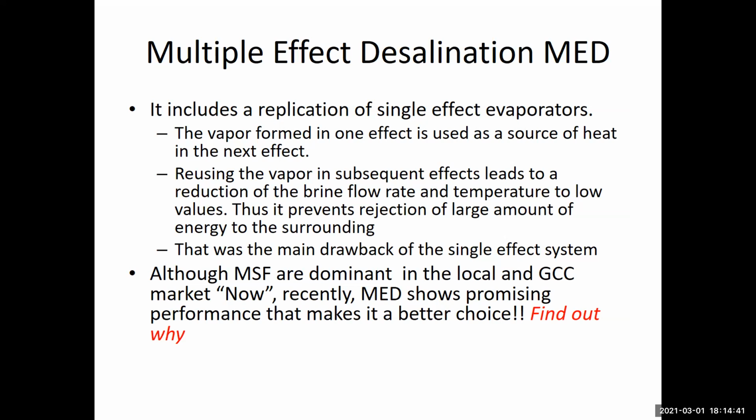Yes, we can. If you are able to do nanofiltration or reduced graphene oxide ultrafiltration to the seawater coming in, then you are able to eliminate the ions that result in scaling, and then you can increase the top brine temperature without fears. When you do that, instead of having 8 effects, you can make them 10 or 12. So instead of having a PR equal to 8, the PR can equal 12, can equal 16, depending on what temperature you are going to reach.